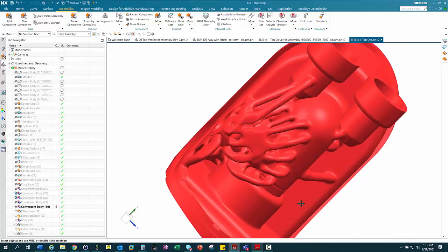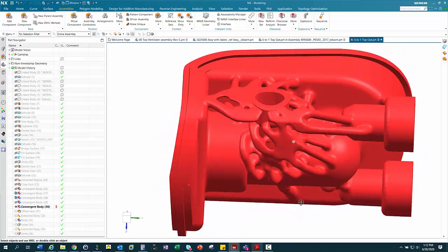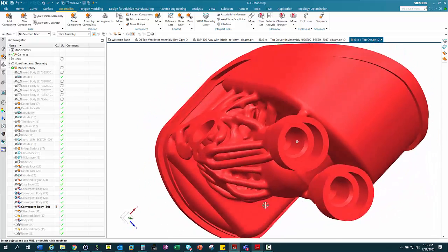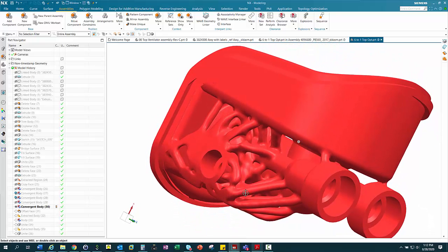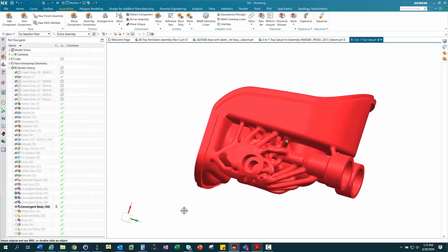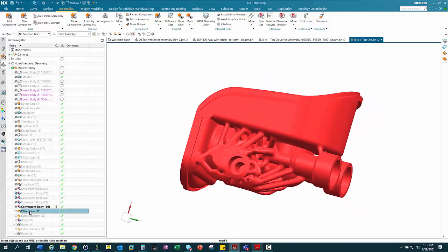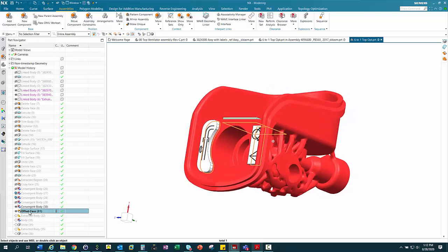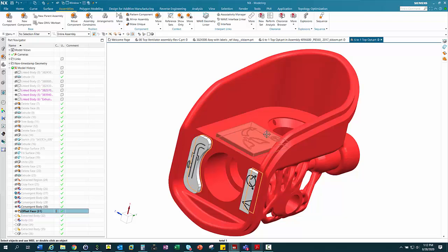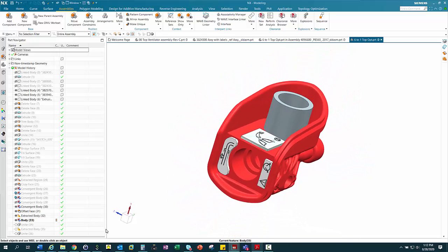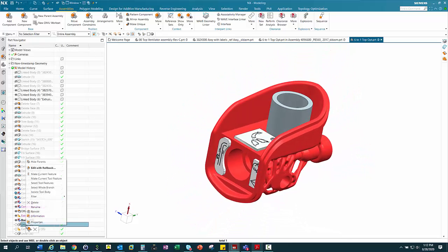This one here, you could control the spread of the material because we're printing it in powder. We don't have to worry about supports. We can get away with a skeletal structure that looks like this. And to make it even more powerful, then we could start using convergent modeling. So we could start doing things like we united these on, and we could start offsetting these shapes, add additional features for improving the model, and unite things together.